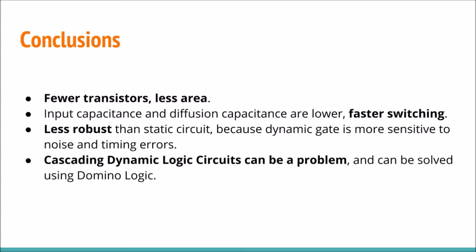Finally, we observed what happened when cascading dynamic logic circuits, and the necessity to implement domino logic in order to evaluate only one stage at each evaluation phase.